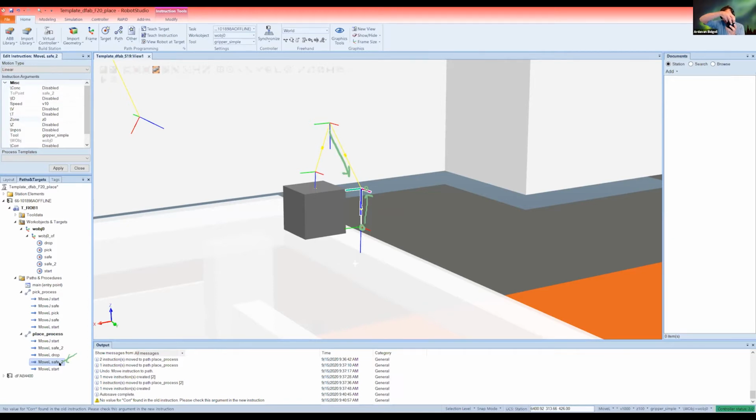Now I want to release this one and come out. If I use move J for retracting from the final target, my hand is going to make a motion like this, which means that I may actually have a collision with the body of this hood. But if I make the exact motion that I made previously, another move L, and come up, then it means that the way I got in, I'm just going to exactly pull back and come back from the same direction.